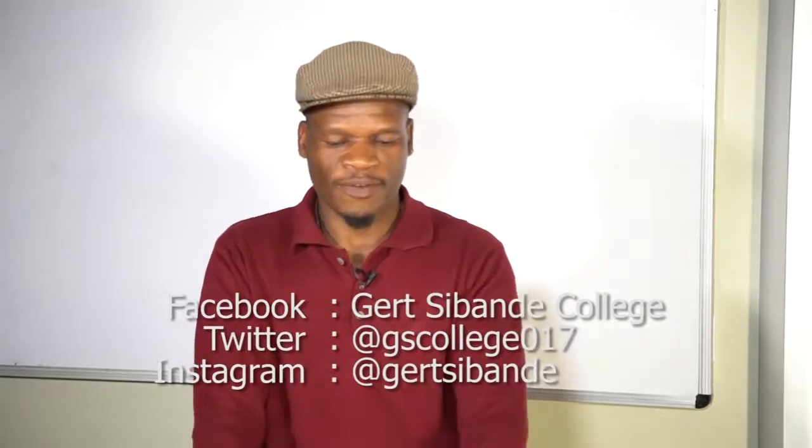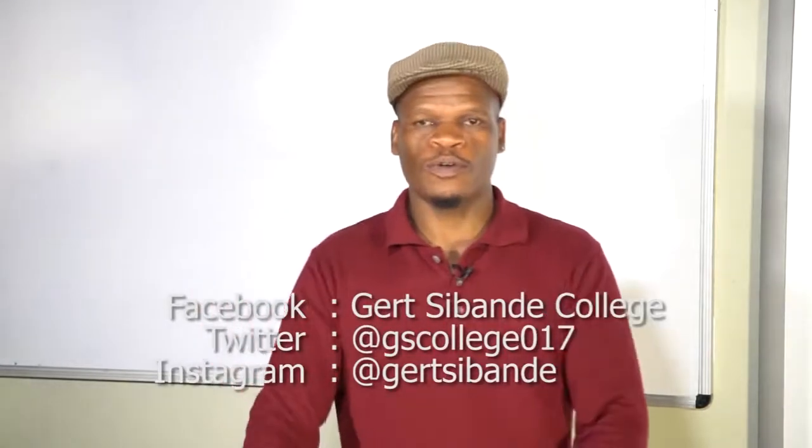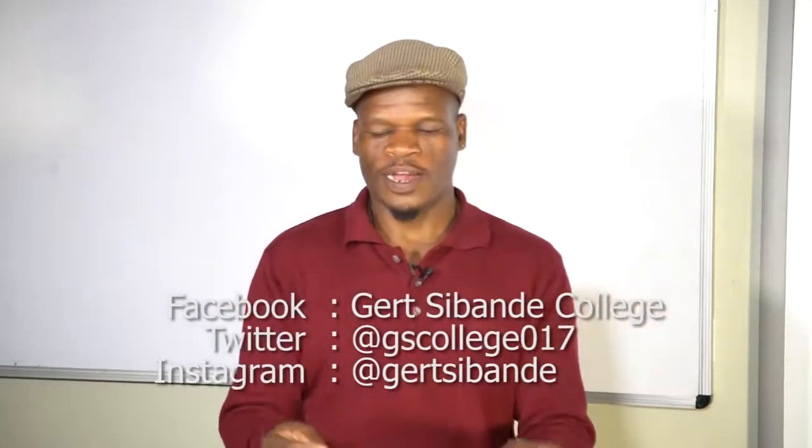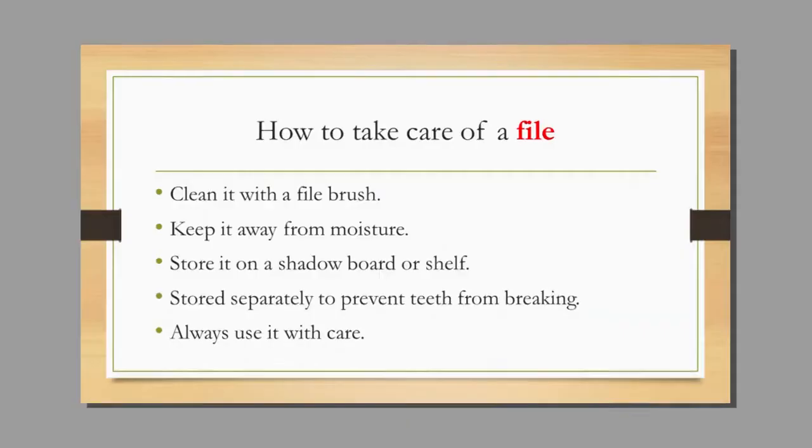Then how to take care of your file. When we talk about the file, we are not going to talk about the file which keeps some documents in. We are talking about the file which is going to sharpen steel, metal. It can be a knife, it can be any tool that will need to be sharpened. If there is any need, you will definitely have to use the file. So after you have used it, make sure that you clean it with a file brush.